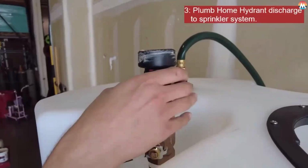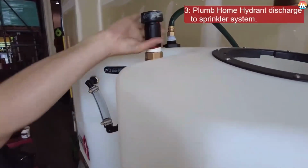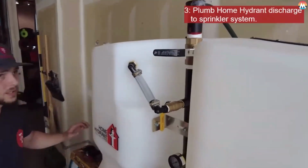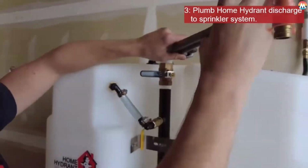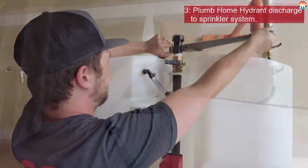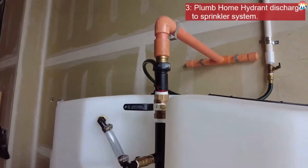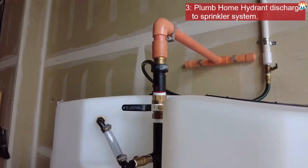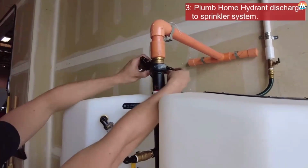Then we are going to hook the home hydrant up to our discharge once we have the tank placed. In our case here, we are using a thread by groove nipple that will go into the thread by slip orange PVC fitting. Then we are using our groove coupling to connect the home hydrant to the sprinkler system. We obviously don't have a full sprinkler system. This is just for demonstration purposes.